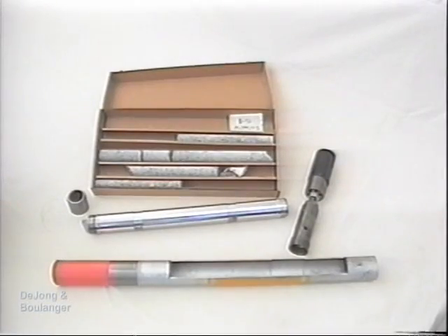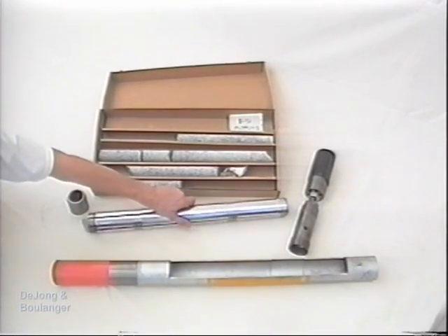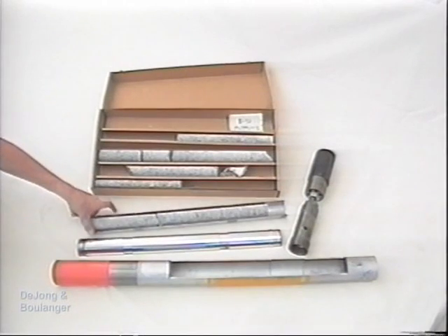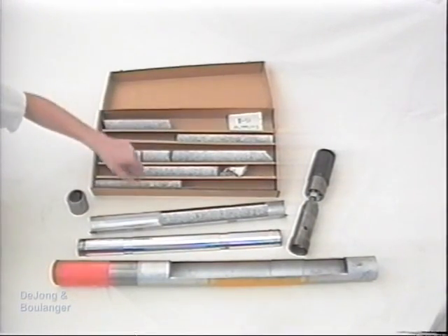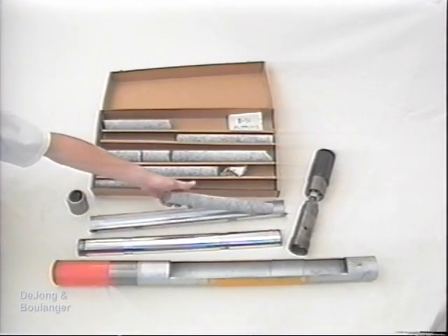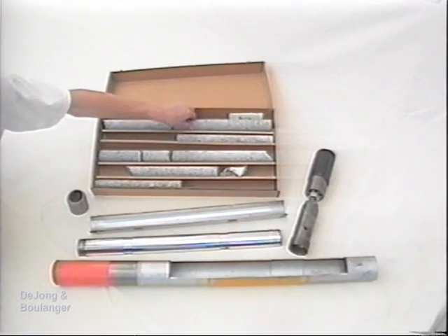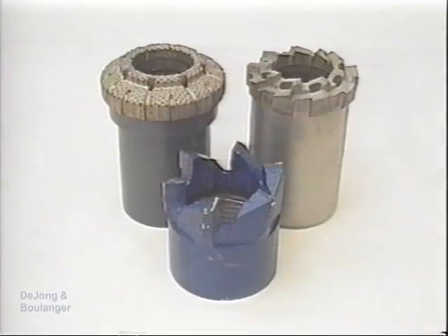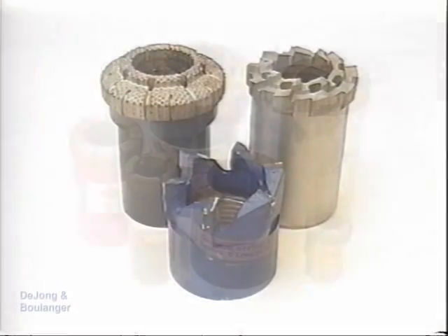By disassembling the core barrel, a continuous sample of the soil or rock is recovered. The sample is measured, identified, and stored in core boxes. After reassembly, the core barrel is lowered to the bottom of the hole and drilling and sampling are continued. Coring drill bits come in three basic types. Pictured from left to right are the diamond, carbide, and sawtooth.